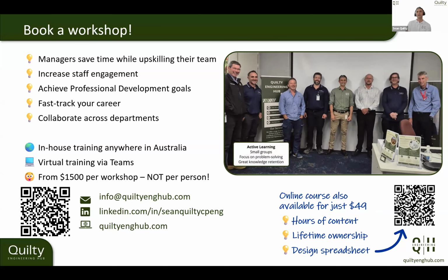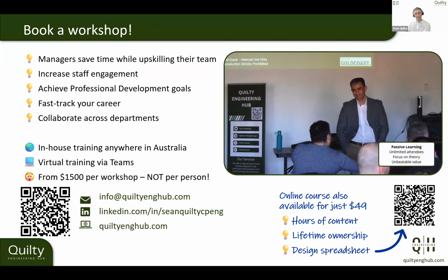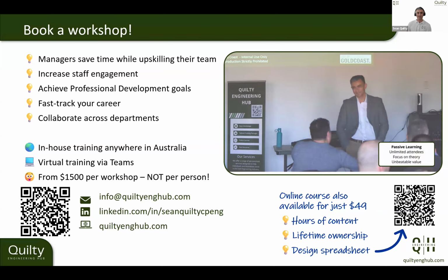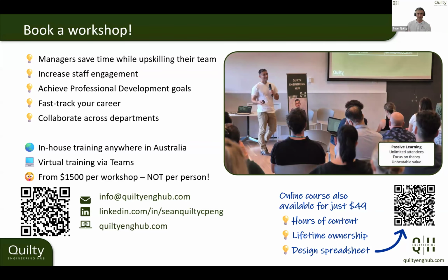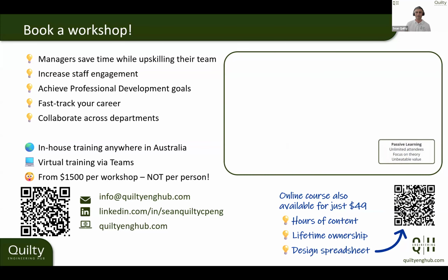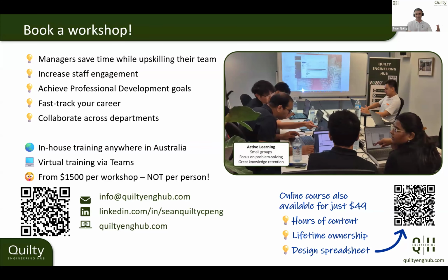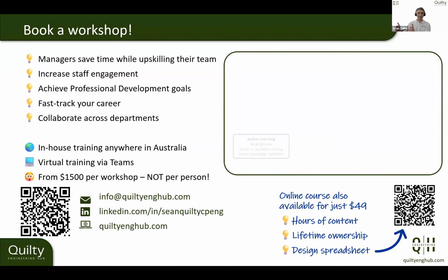So that's one example. Then when they don't maintain this channel, or you have summer, you get a heap of rain, you get a heap of heat, and everything just explodes and grows like crazy. All of a sudden, the grass is like 250 mil high, weeds, there's sticks all caught in and everything else. I would also design the channel for that condition.